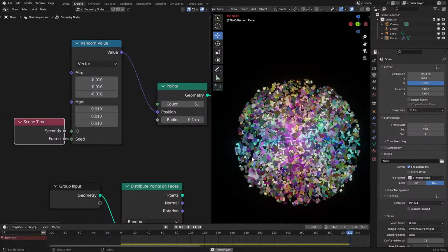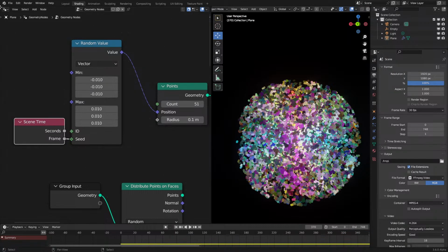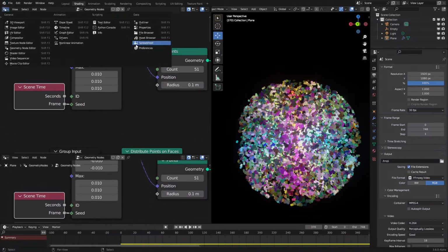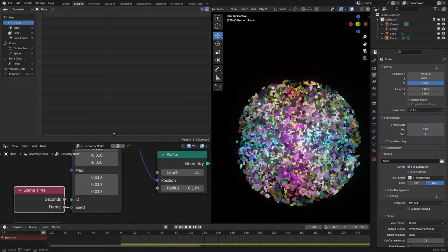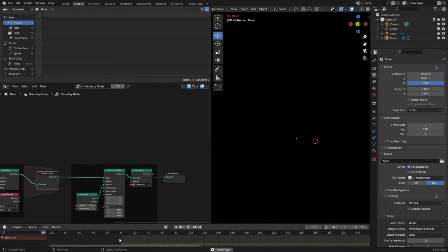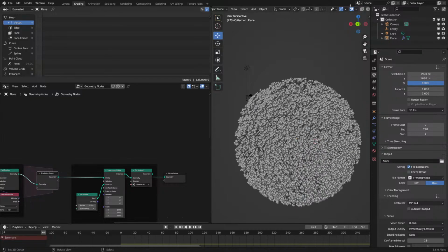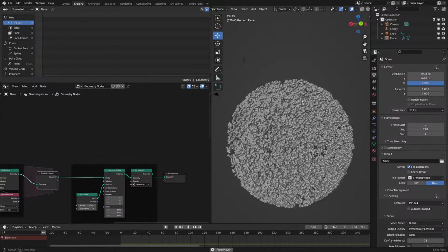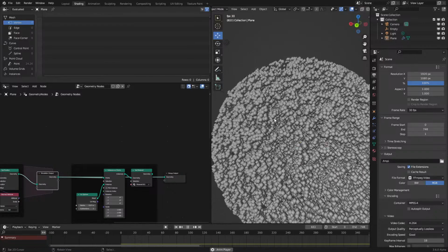But unfortunately, it starts to lag because Blender cannot handle... How many particles is this? Spreadsheet... It's not even 20,000. Huh. Actually, I need to check something. Is this... Okay, it is. So the lag is a result of the instances, not a result of the particles simulating themselves.